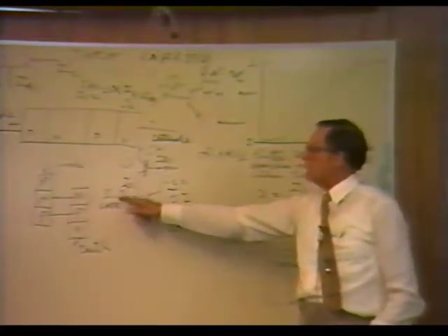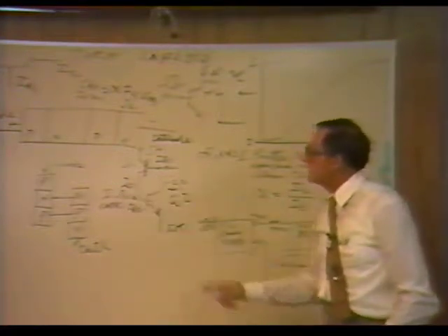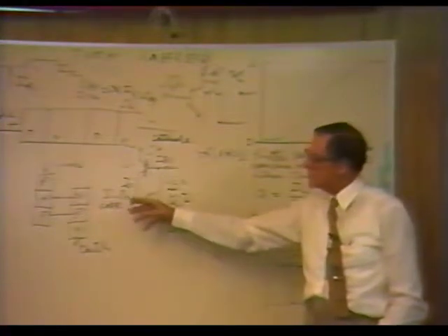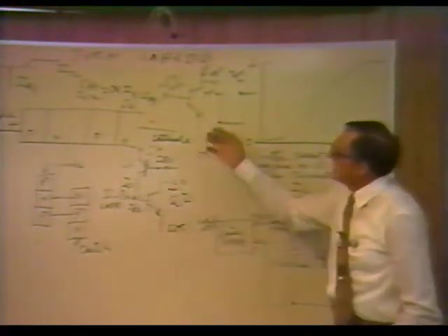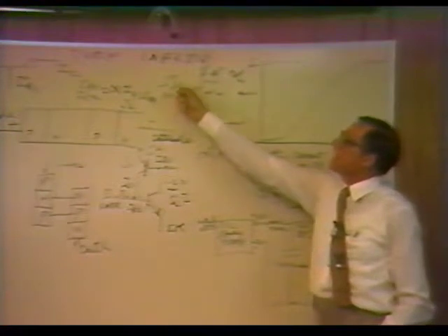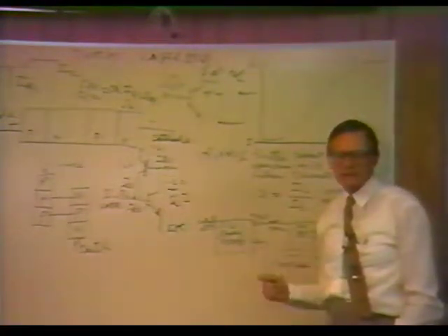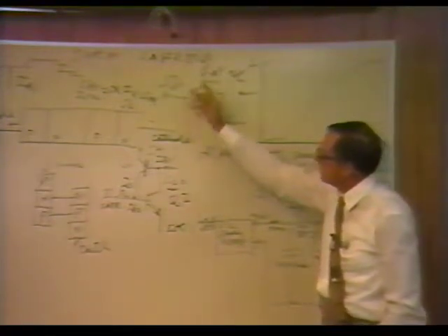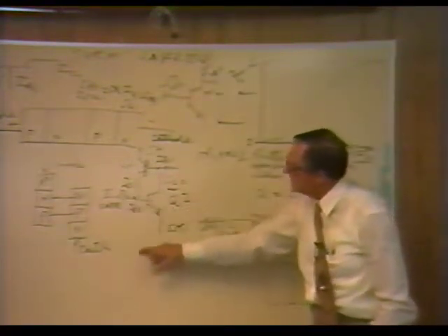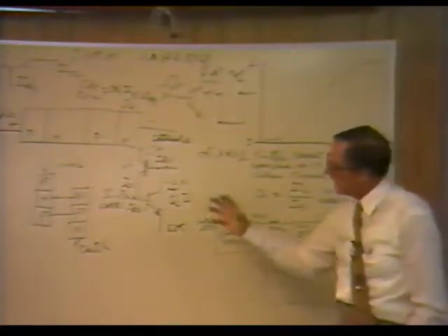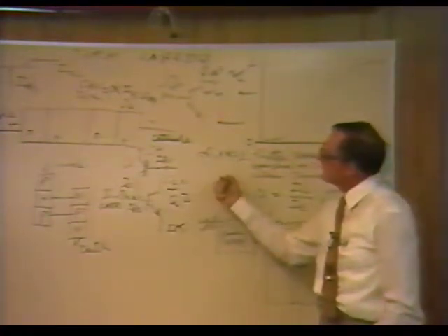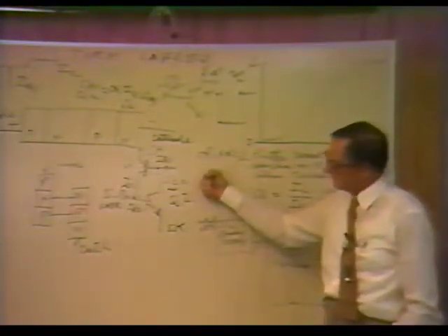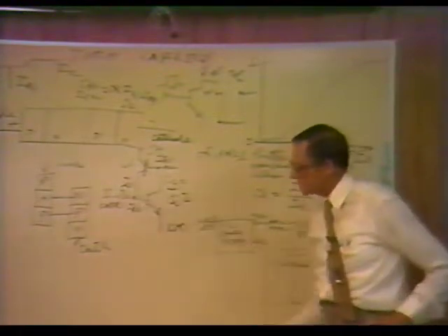In an SCR, I have to have a very short pulse of maybe 5 to 10 mils, depending on how sensitive the SCR is. If I had to build a circuit to supply 200 mils to keep that on for a short period of time, I'd have to have a fairly large circuit to supply that current, and when I took it off, it would stop. On an SCR, I need only a spike. So a very low control current can influence a very high load current. I can turn it on with a very easy pulse.